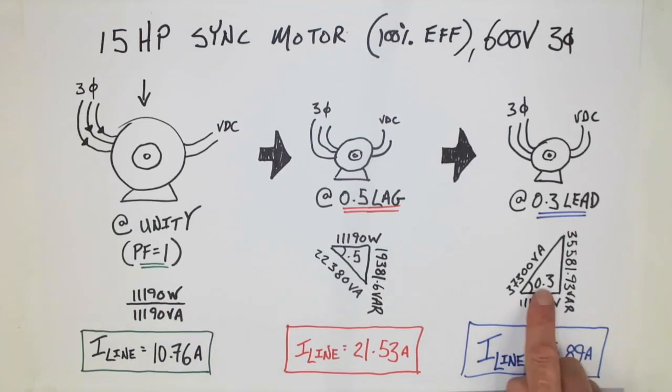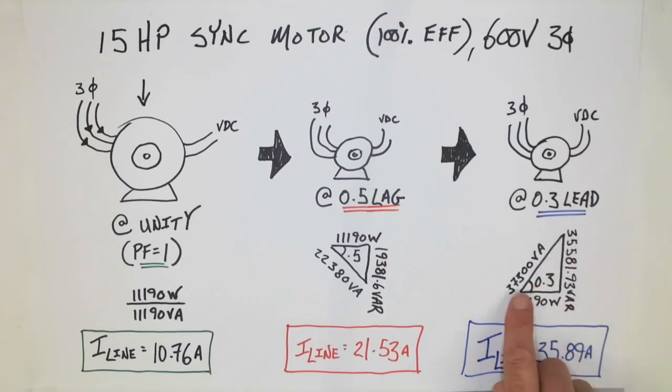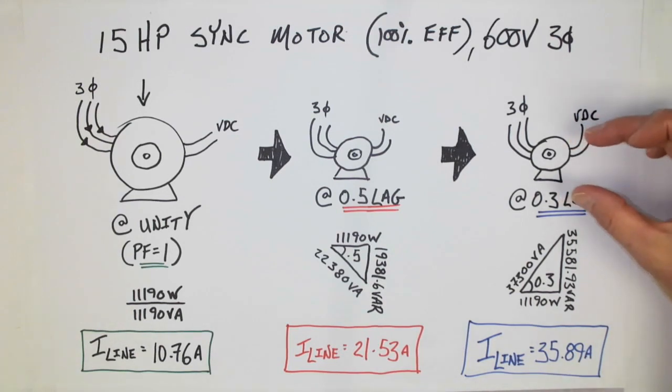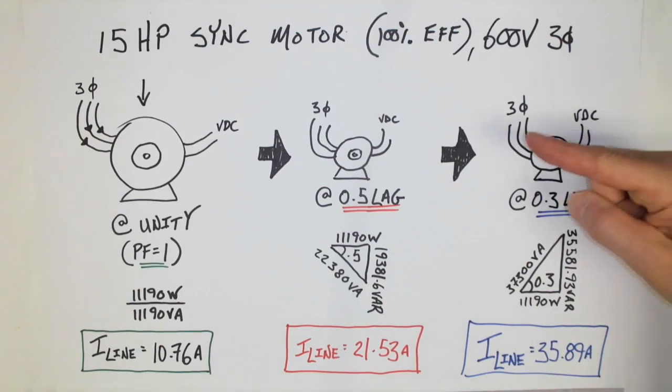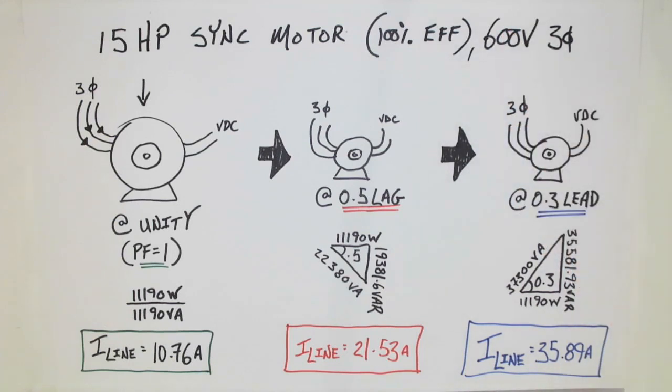However, with a 0.3 power factor, we see 37,300 VA, which then, of course, leads to a much higher current. Again, because this is AC, consider once we go into leading, try to imagine that this item here is more supplying leading VARs back to the supply authority, as opposed to drawing that current in order to run.